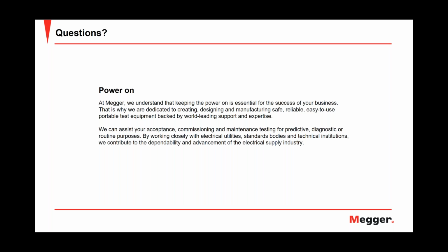All right. So Henning, what does TDR and ARM stand for? Oh, TDR stands for time domain reflectometer, because like Javier was explaining, many people believe it's a distance meter. It's really an impedance meter. It measures impedance in the time domain, and that's where the name comes from. So we're looking at changes in impedance along the cable.